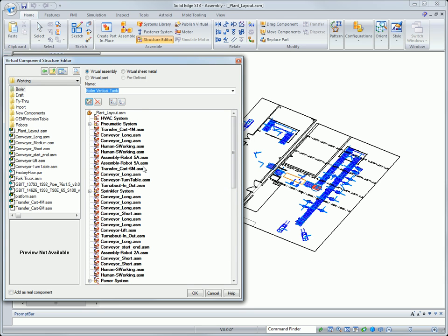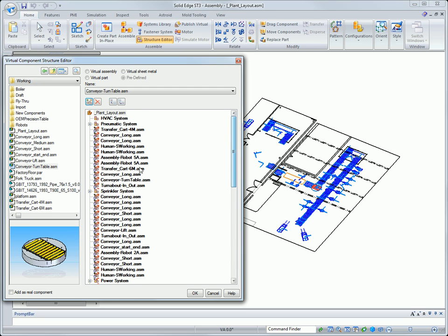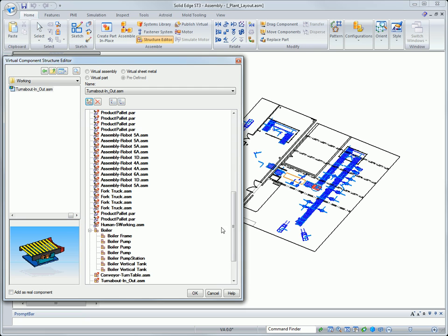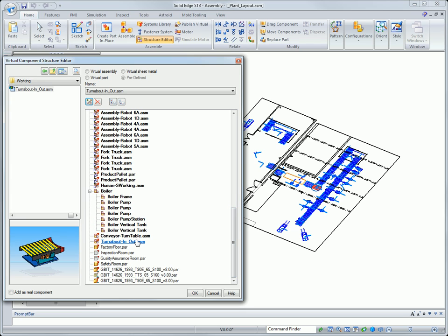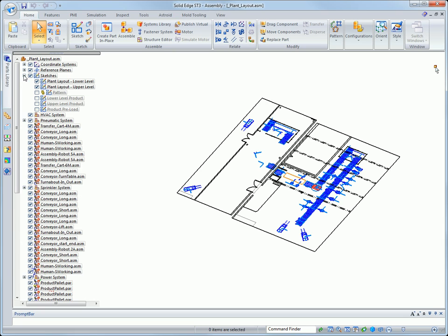We can also add real parts and assemblies to our design. While you may expect to see the physical 3D components when we're done, Solid Edge has some built-in optimizations that we'll look at a little later. Now the assembly tree lists the new virtual components and they are in the right spot. Keep in mind at this point no additional files have been created. We'll do this later. Thinking about the power here, we have no files to manage and performance will be optimal. This is just the thing needed for working with massive assemblies.